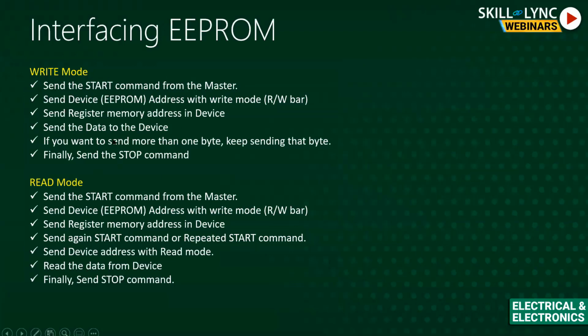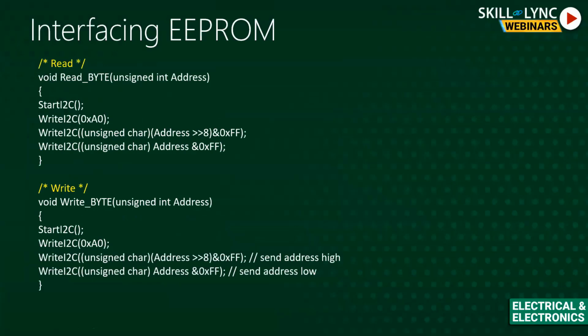The only difference here is that you need to send the start condition again in case of read, because first you will send the start command, then you will send the address and other things, and again you will send the start in case of read. It is not required in case of write. In a similar way, you can create your own code to send those addresses and perform the read or write operation.